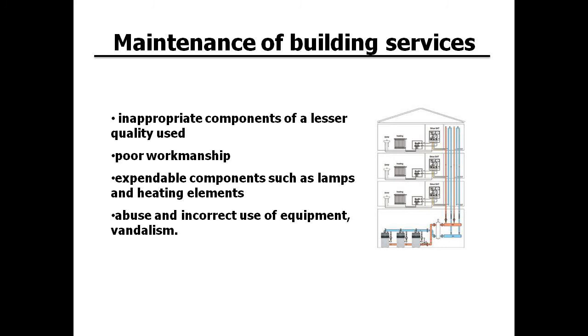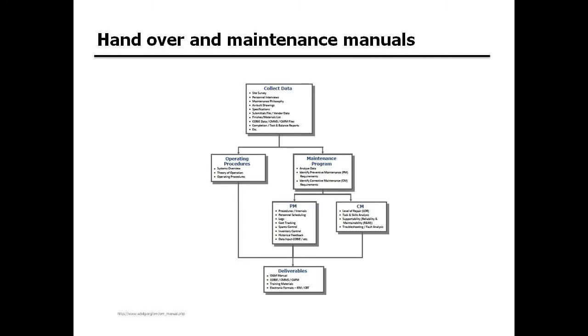Furthermore, availability of parts. I myself have experience where fire panels, an integral part of the fire protection system. Having said that, fire panel use can be 15, 20 years, no problem. Once parts are not available after 5-6 years, it's very difficult for that particular piece of building plant to actually be reliable, or to confidently say that it's going to achieve what it should in fire protection.